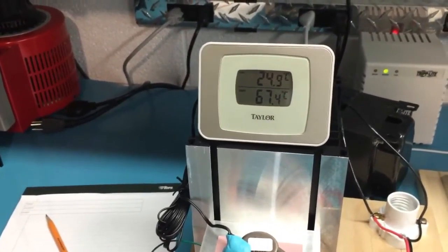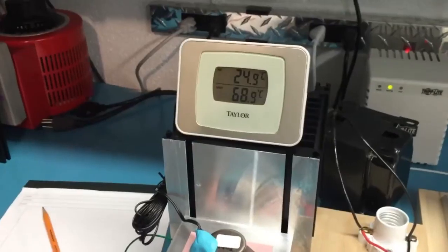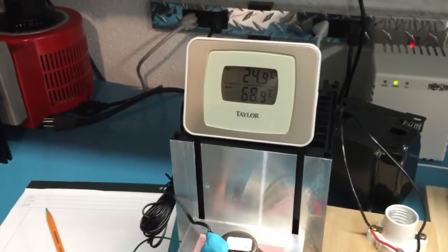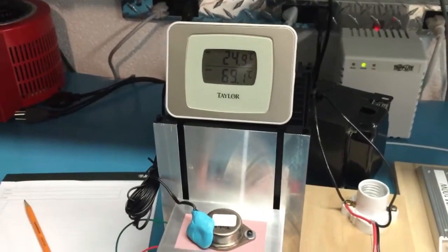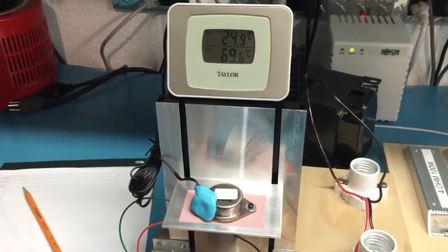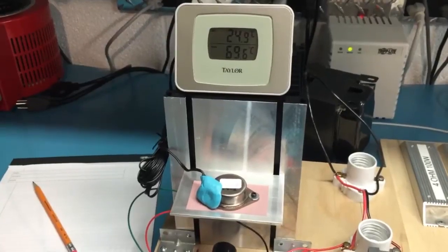Case is at about 67 degrees right now. And so when we keep the gate voltage the same and we heat up the part and the drain current goes up, that is a positive temperature coefficient. So there you go. Now I should mention that I was taking some readings, and the gate leakage current is pretty temperature dependent, and so that might be contributing to the positive temperature coefficient a good bit.